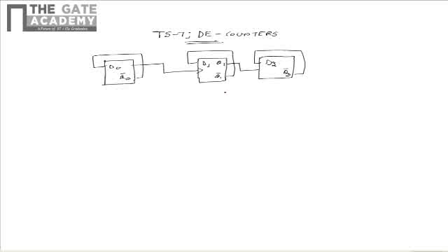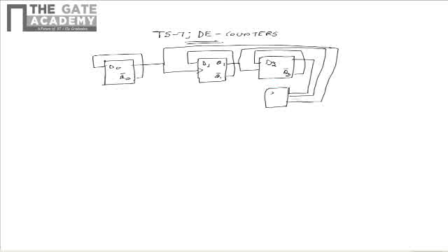And it is also given that these clock signals are given as inputs to a feedback logic, and the output of this feedback logic is given as an input to the reset signal of the three flip-flops. It is given that all the three flip-flops are cleared by a 0 input at the R input. Now we need to find out the correct feedback logic.